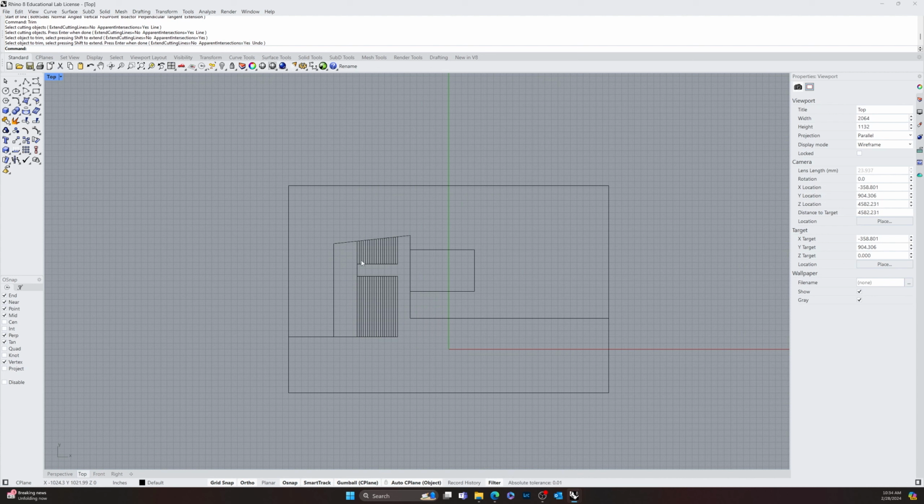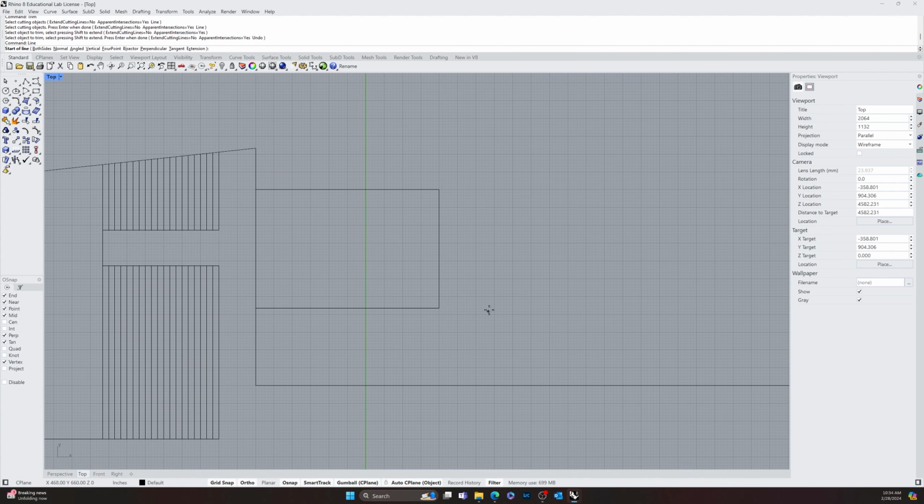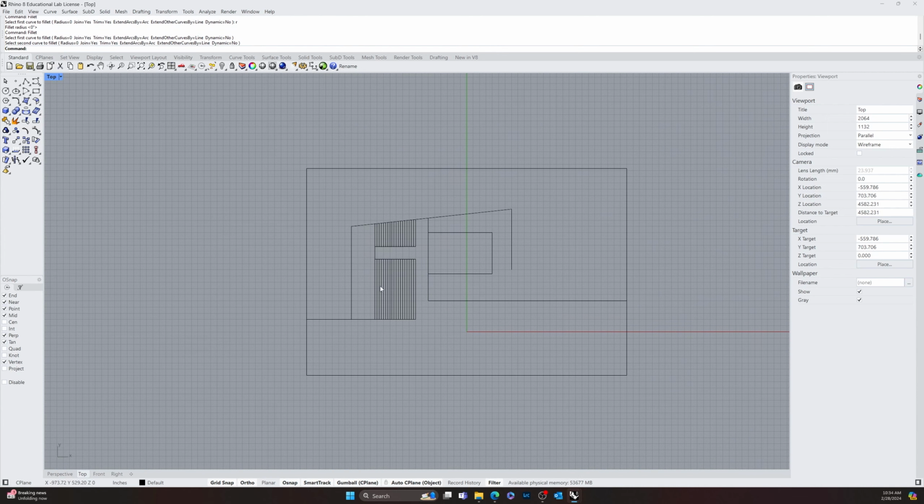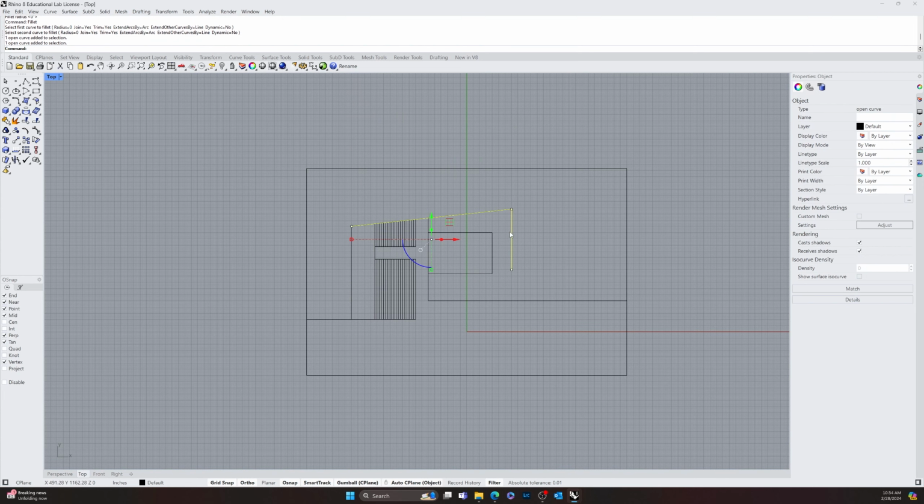Okay, so I'm going to just build my second story here, and I'm going to draw a line maybe right around, let's do this far off here. And then I'm going to extend, or you can actually fillet, which is nice, with a radius of 0, R0, enter, and then click on this, and it'll just create a nice straight line there. And then actually, I think I might mirror, well, I made it all one piece. Let me explode that. Mirror this